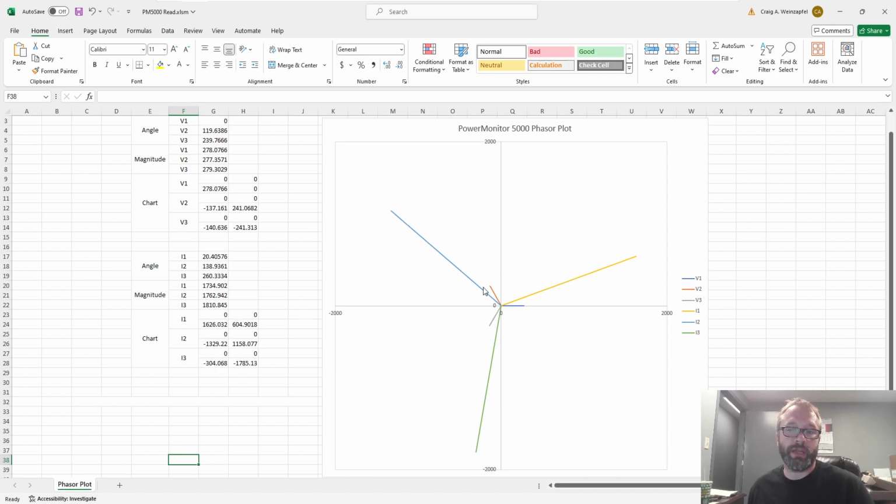It should have been at the green line, and where it was when it was swapped. And then the same with phase B, and then a really large angle, an obtuse angle actually, between phase B voltage and where phase B current was measuring when the CTs were incorrectly installed. We were getting normal numbers on phase A. We would get the correct kilowatts, the correct kVAR on that phase only. Phase B and C were not mirrors of each other, or just inverses or negatives and positives of the same number. They were really quite out of whack.